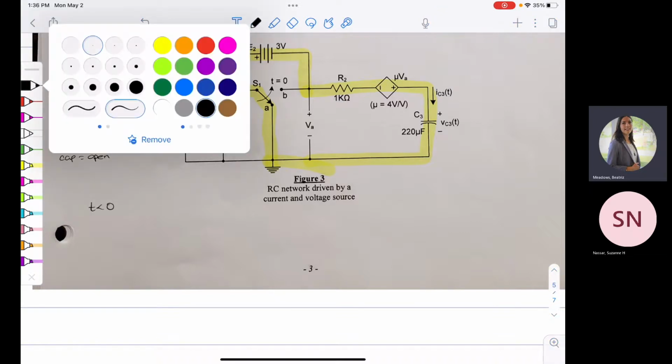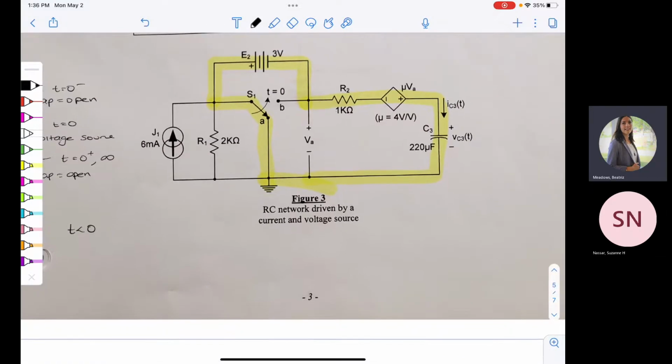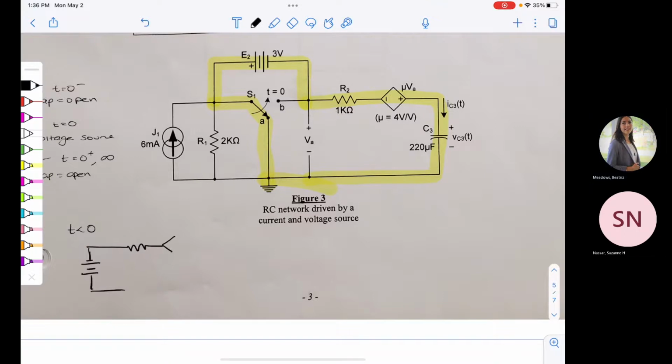That's why if you put a short next to your resistor in parallel, you're going to short your resistor, because the current's going to go through the short. What if it's in the middle? Then it will go through the resistor. If there was a resistor in the middle, then you'll have a current divider, because current will go through all three branches.